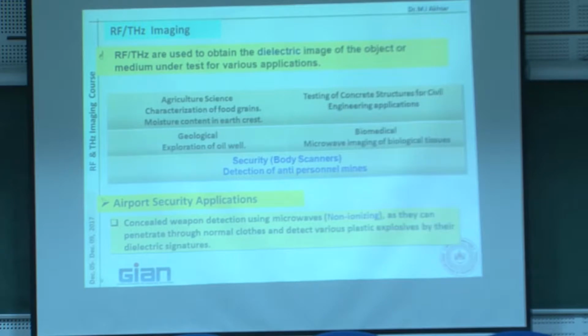No, I didn't say you use imaging to find the permittivity. What I mentioned is that characterization is the first step towards imaging. If you have a substrate, usually people say it's homogeneous, so you just want to know its permittivity, and you know its thickness, let's say 1 mm. That doesn't come under imaging, it just comes under characterization. But it is also important, because if you don't know the permittivity, you cannot go to the next step, which is the imaging part. Apart from designing normal circuits where you need the permittivity value, if you want to use imaging, you can only distinguish different regions by their permittivity. So that was my point. Okay.